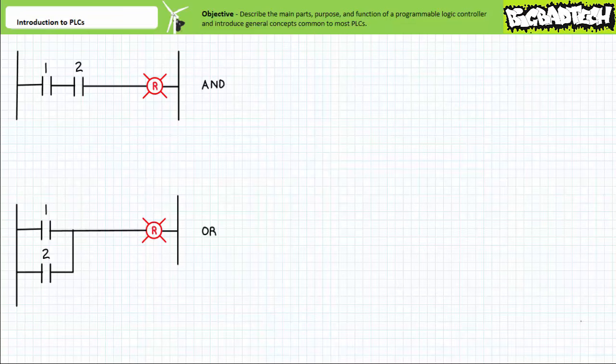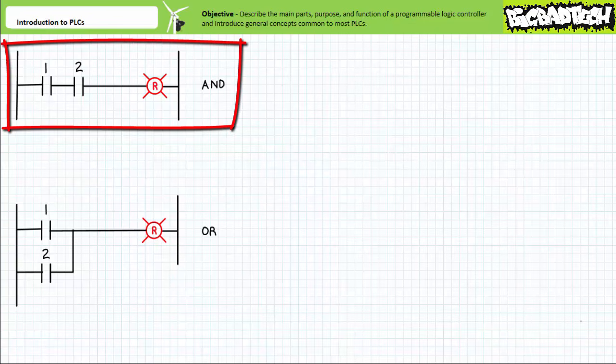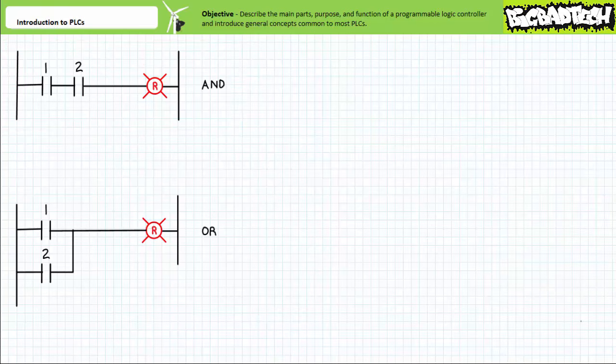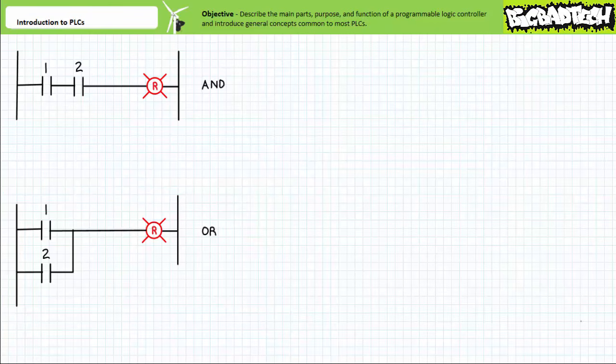is available and encouraged. As we've previously discussed, logical operations of immense complexity can be created by hardwiring input devices, relays, and output devices in a prescribed fashion. The classic example is the logical AND operator formed by the series connection of two normally open contacts. Contact 1 and Contact 2 must both close to assert the output. In contrast, the logical OR operator is formed by the parallel connection of two normally open contacts. Either Contact 1 or Contact 2, or both of them together, can close to assert the output.